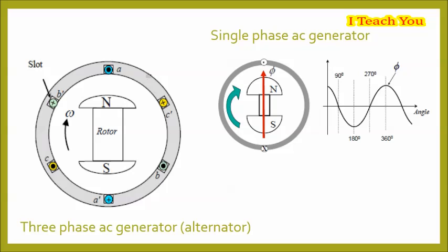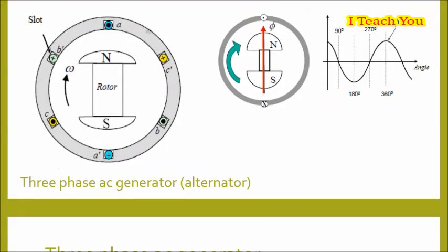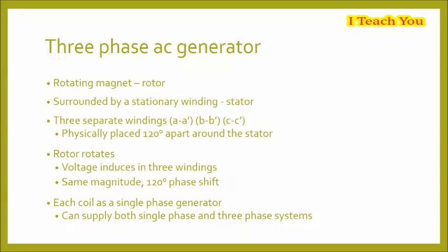In a three-phase AC generator, there are three windings. Each winding has two terminals, start and finish. If a separate load is connected across each phase winding as shown in the figures here, then each phase supplies an independent load through a pair of wires. Thus, 6 wires will be required to connect the load to a generator. This will make the whole system complicated and costly.